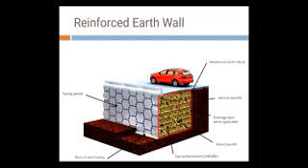But the panels alone are not capable of restricting that. So that's why soil reinforcement, that is the white strips, metallic strips, has been introduced. And the selected backfill has been compacted. Why? Because over it there is a road passing. And there is a reinforced earth block and base.